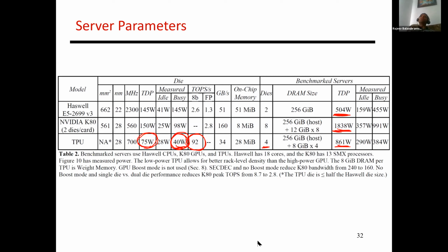You could also use a paper from Stanford which talked about how efficiency is lost as you go from an accelerator to a general purpose chip. It basically says that as you waste energy on instruction fetch and decode and all that, that makes a chip less of an accelerator and more of a general purpose unit. So you could use even those quantitative metrics to decide if something is more an accelerator or more a general purpose CPU.